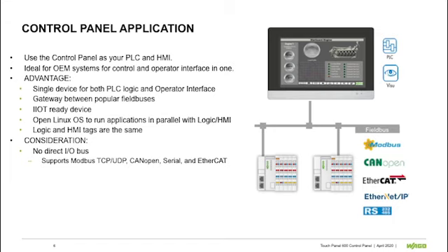So when using a control panel, you need to consider that there is no local bus, so you can use one of the supported field buses to connect to distributed I/O. And I would also note that via field bus you can exchange data with WAGO and third-party PLCs.